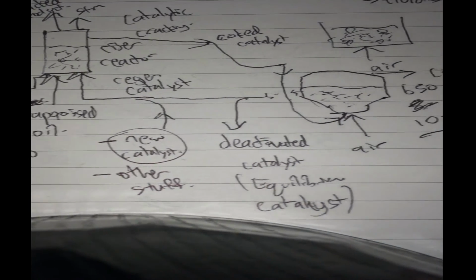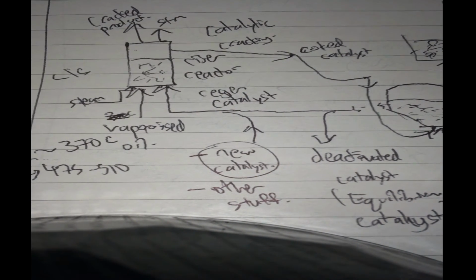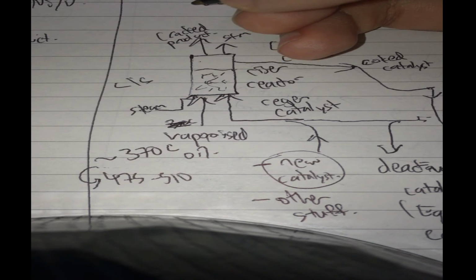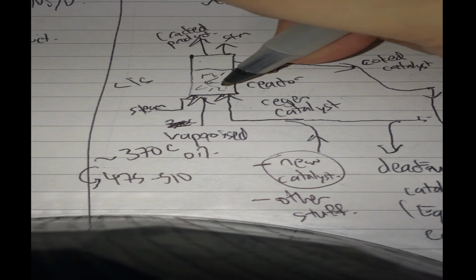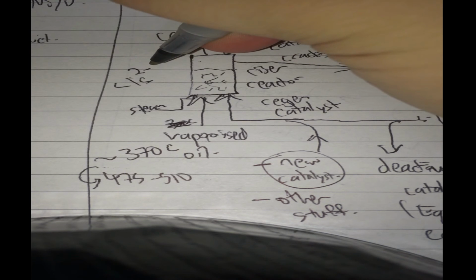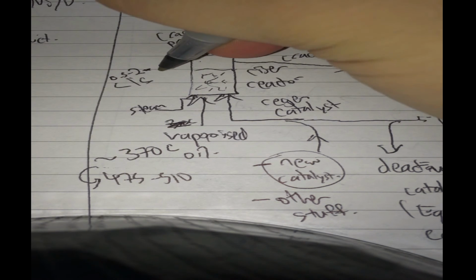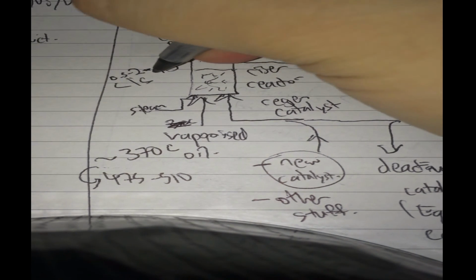And what is the pressure around here in these two? Because you need to fluidize it, there needs to be some pressure to force air through the powder. So you are looking at around 0.5 to 2 bar gauge.